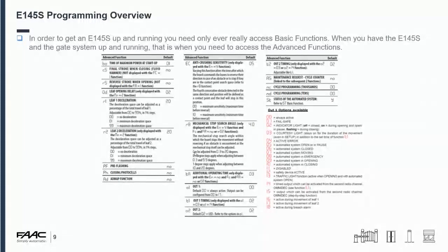One of the things I'll say with the encoders, if you are fitting gates onto, say, large boarded gates, and you're using force testing as your safety system, the encoders will probably need to be switched right down to minimum sensitivity. Essentially, you can't get an encoder that's going to be able to pick up the difference between a stall from a wind or a stall from hitting somebody.